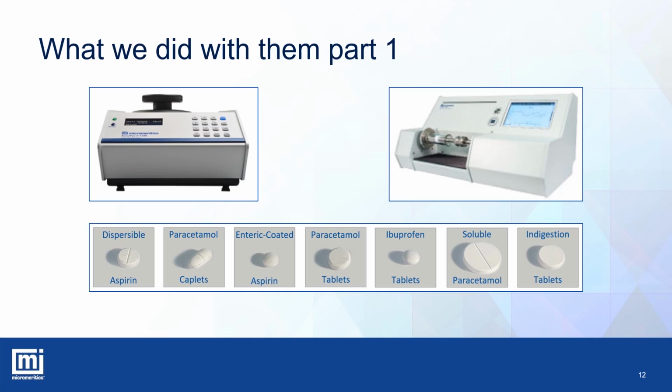We took a range of over-the-counter tablets and measured them with both devices and generated envelope volume and density, skeletal volume and density, and porosity values for each tablet type. They were measured as multiple tablets in each sample to simulate the kind of in-process testing you might do. This is fully described in App Note 180.